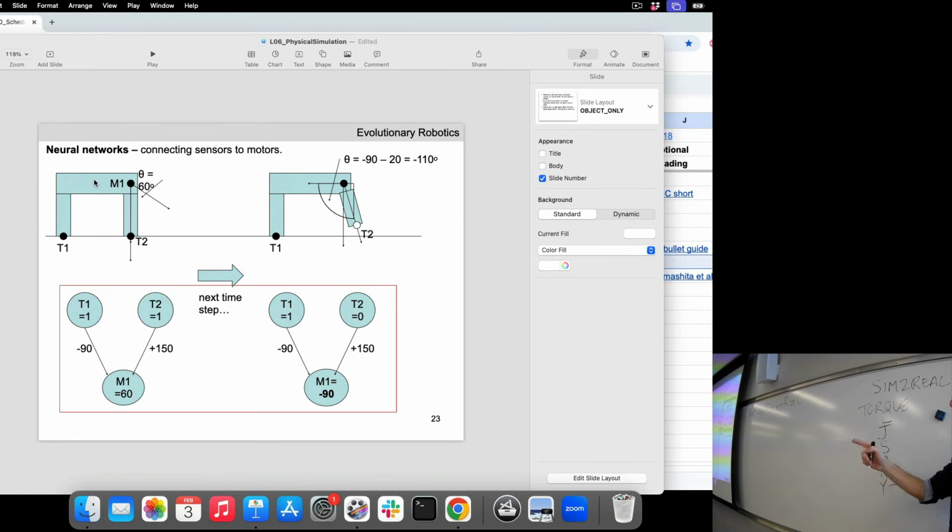So we know that the real robot is going to weigh about 170 pounds. The front leg is going to weigh about 30 pounds. We might work backwards to what's the maximum amount of torque that's going to be needed. If you've got a 140-pound body and a 30-pound front leg attached, a hobby motor probably ain't going to cut it. You're going to go looking for a different motor, right? So yes, we're trying to make decisions here that inform how we go about doing this. We're going to spend a lot of time talking about exactly this in a few weeks' time.